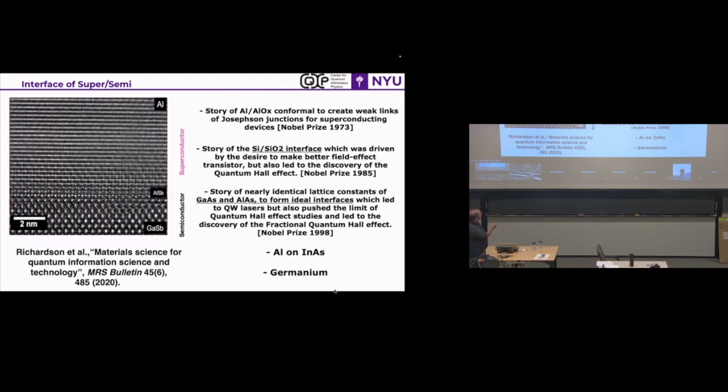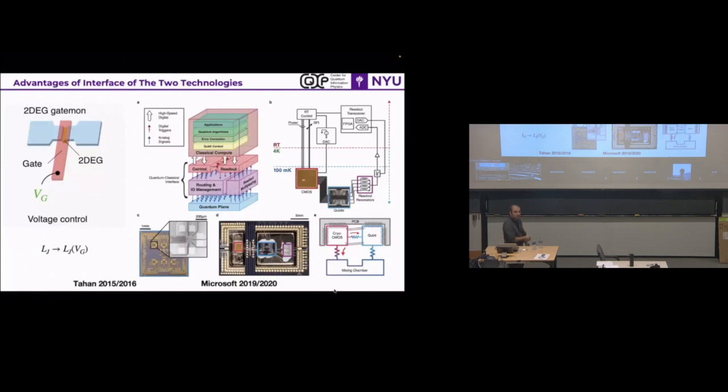With the proper way that we are growing this with MBE, we can get, this is a 2 nanometer scale bar. You can see exactly how I transition to a superconductor. And if you look at the lattice of aluminum, it's much smaller than indium arsenide or gallium antimonide. But then magically, 5 atoms of aluminum match exactly with 2 unit cells of indium arsenide and create a perfect interface, as if they were a perfect match, right? So this is something that we are trying to build on.